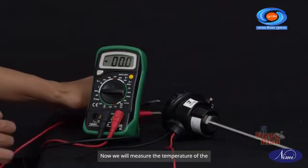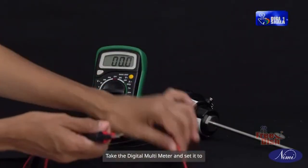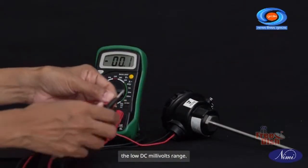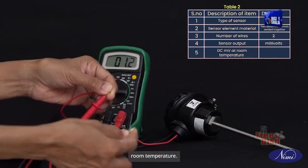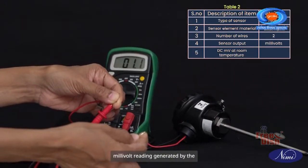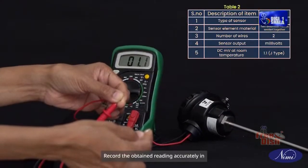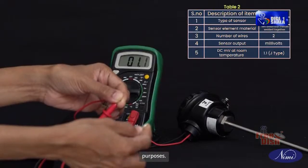Now we will measure the temperature of the thermocouple at room temperature of type J. Take the digital multimeter and set it to the low DC millivolts range. Place the thermocouple in an environment at room temperature. Using the digital multimeter, observe the DC millivolt reading generated by the thermocouple at this temperature. Record the obtained reading accurately in the table for future reference and comparison purposes.